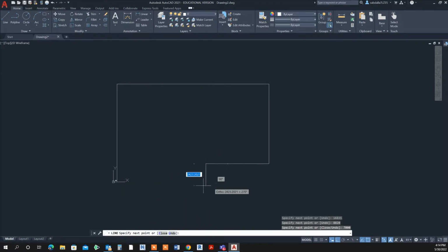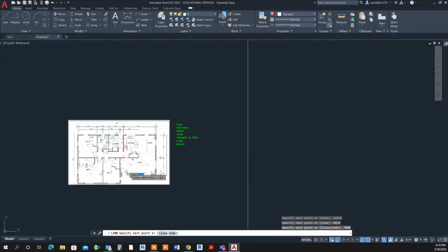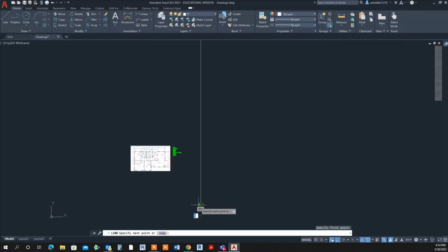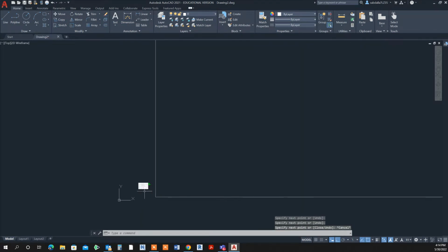Okay, so let me see what else I can do. I have a small dimension here, which I also don't have, but this dimension will align with this one. So maybe I'll draw this dimension. I'll go back and start from here. So line, start from here. And now I'm going to align with this line here because I didn't have the dimension. So I'm just going to track. When I move my mouse, there's a green check and a green line, that means I'm going straight, and then I close my plan. So these are my outer lines.